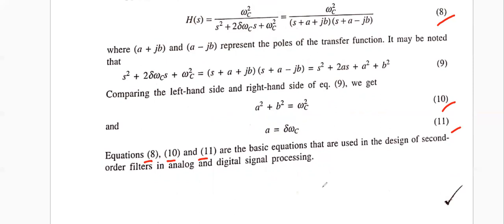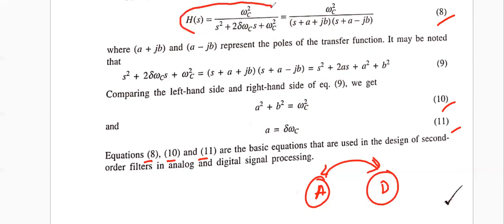So you can go from analog to digital with these functionalities, because in case of analog filter design, of course the things are based on the cutoff frequency, and also in the discrete domain we need the cutoff frequency, as well as we need to plot in the z plane. In case of the S domain, we need to plot it in the S plane, as we have mentioned earlier. But that means we can design the filters in the analog domain like this, and we can move to the pole zero locations like this.